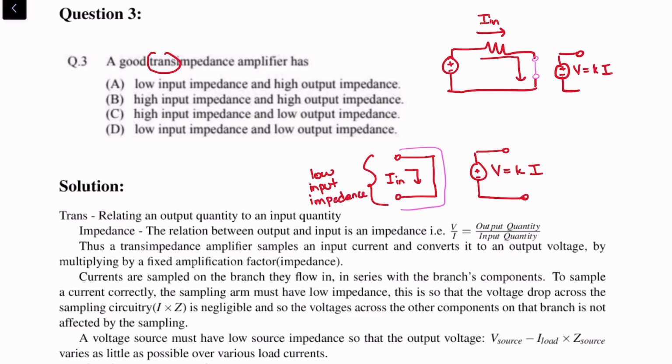right? And of course voltage source, so an ideal voltage source, as you can see, does not have any resistance in series with it, right? This is a practical voltage source. It would have some source resistance in series with it, but the idea is the more and more this R_S tends to 0, the more this combination behaves as an ideal voltage source, right?